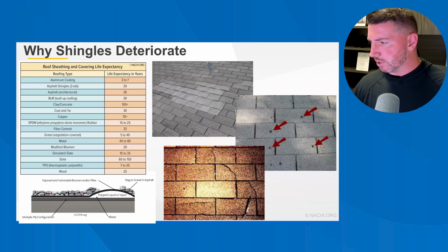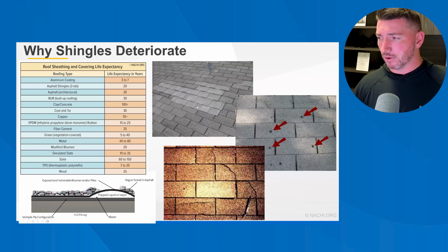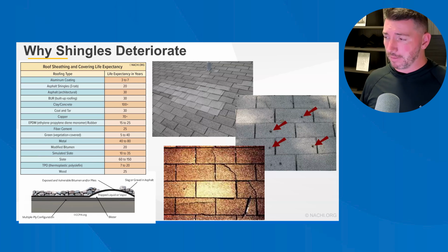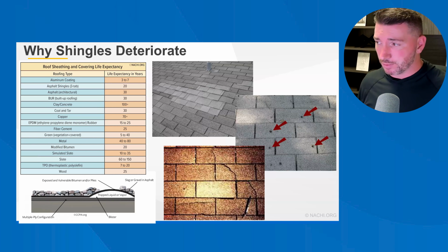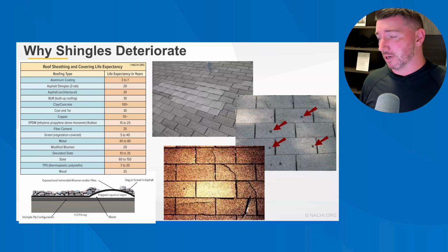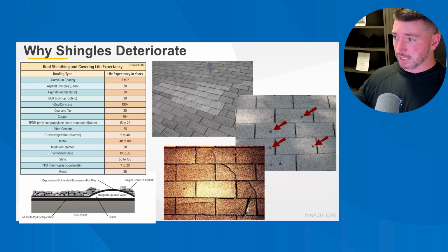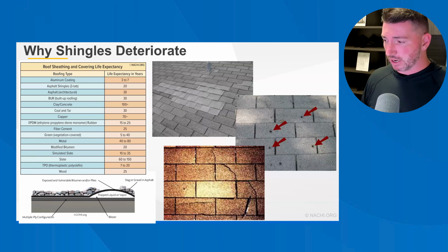And what you can see in the photos is basically an improper repair on that top middle one, where you've got a roof repair that was done where they used more modern laminated shingles in place of those 3-tab shingles. Those exposures are not going to match up, so they're going to be very difficult to nail in. I certainly wouldn't do that. It's an installation defect. You're going to build up excess heat, and those shingles are going to degrade pretty quickly.